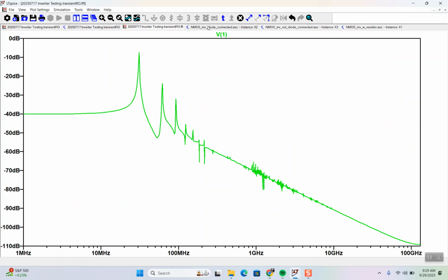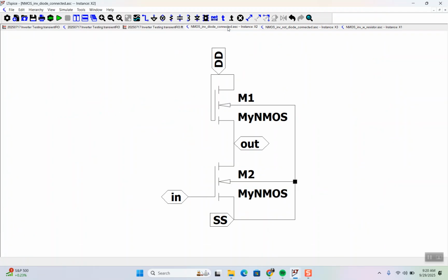why it got faster, we just do here, is that we made the resistance of this lower so that when this turns off and we're charging high, the RC time constant is lower, so it charges up faster.